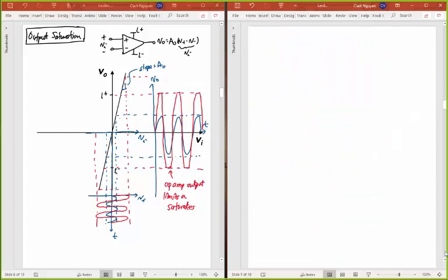And the next one I want to cover is slew rate. Well, no, first let's do finite input and output resistance. That's something you've sort of seen before, but let's make sure we cover it in detail here. And I'm actually going to also show something that you're going to need to use in your homework assignment, especially when you do SPICE. So you know already that all amplifiers, all practical amplifiers, will have a practical finite input and output resistance.